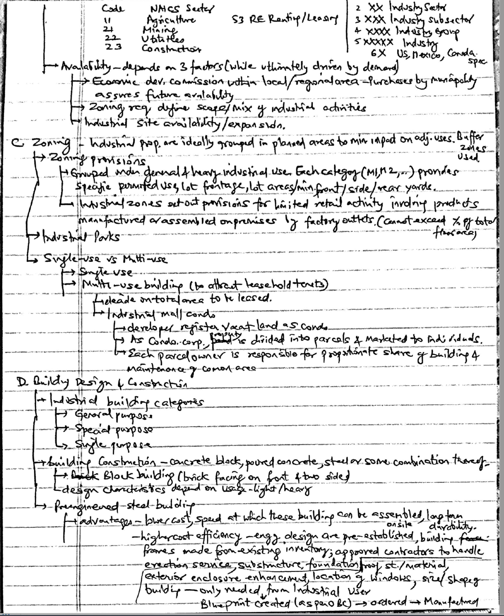Flat roofing. Flat roofing is most commonly found on industrial structures. The term flat is misleading, as flat roofs have some degree of slope for water drainage. Slope refers to the degree of rise. For example, a 4 by 12 slope means that the roof rises 4 inches every 12 inches of horizontal run. Industrial roofs have very low slope as compared to the higher slope in residential property. Residential roofs are not watertight but rather shed water given the high slopes. The industrial flat roof must be watertight along with associated joints and seams.